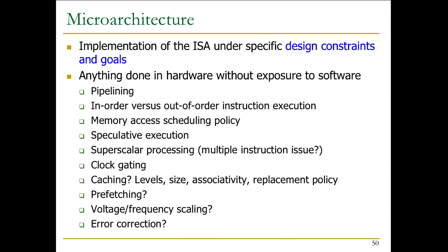When you don't need that high frequency in your processor, you can reduce that frequency. Is that part of the ISA or microarchitecture? Again, the same thing. If it's done purely in hardware, then this is part of the microarchitecture. But in most systems today, this is exposed to the ISA, at least some part of it, maybe not all of it. Because there is a range for voltage and frequency, and some part of that can get exposed to the operating system such that the operating system can do this voltage and frequency scaling dynamically. But you may not need to expose all of that if you do it internally.